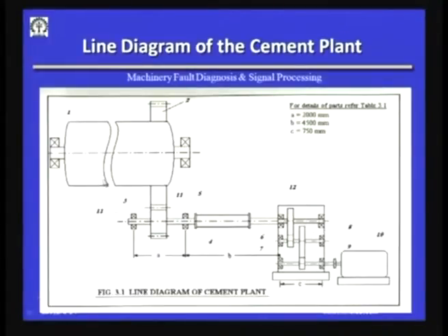in this drum there are very, very hard stones or rolling kind of rocks. It is like a tumbler, and this drum diameter could be about 2 to 3 meters, and this length could be about 7 to 8 meters, and there is a small inclination between this feeding end and the delivery end, and this could be about 2 to 3 degrees slope.